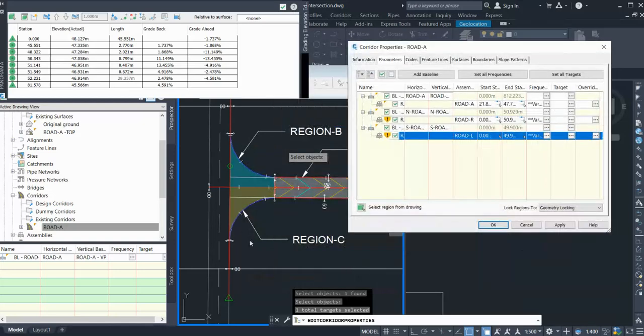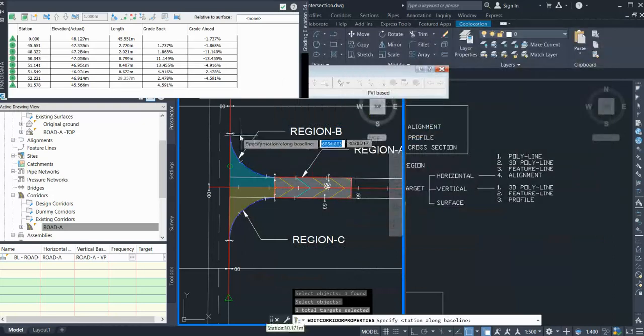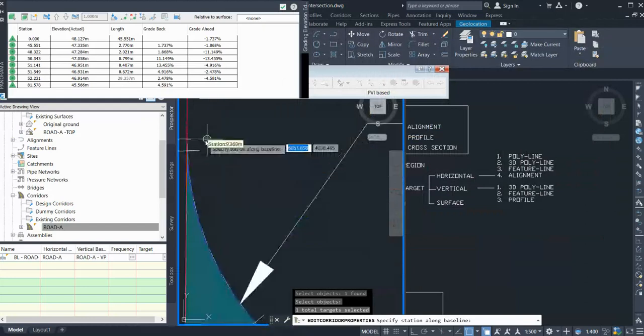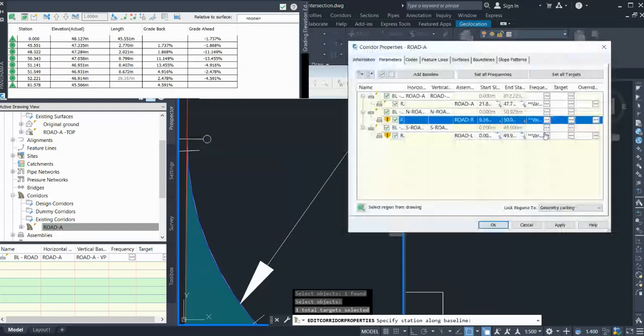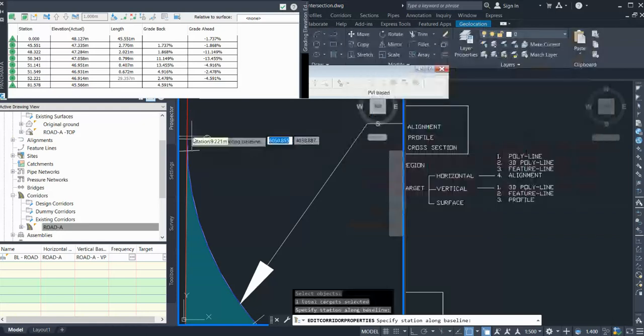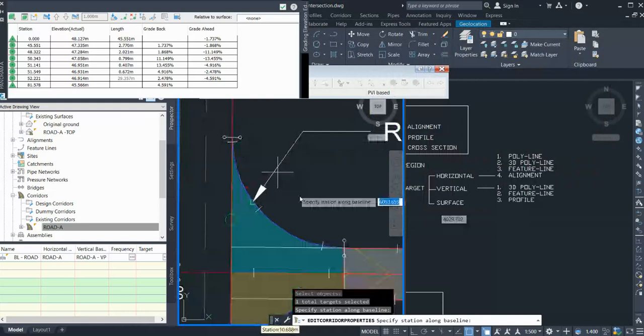Now the next thing you need to select is up to where this region will run. So you have to select your chain edges. From the south, it will start from this end, because this overlapping area we have just taken to get the slope and level of the existing end. So we are not modeling this bit of region, we are just modeling this region.